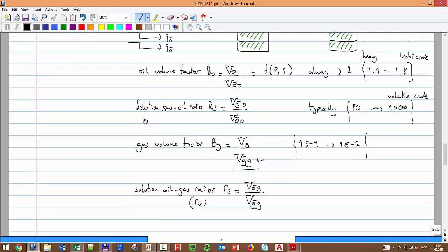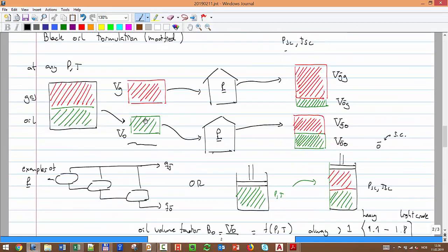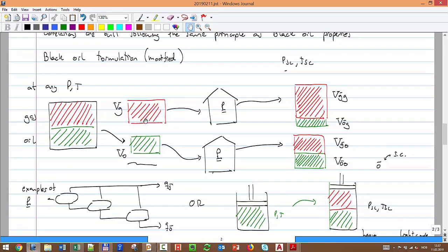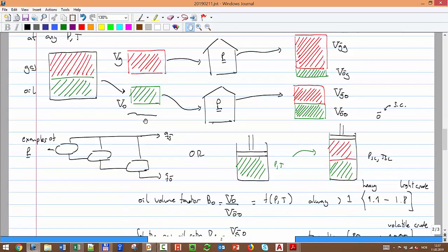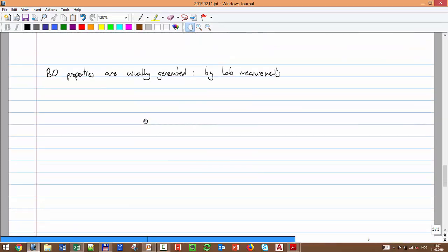I don't want to go into how they look with pressure and temperature. Just see that you have a ratio, and that's very practical, because if you have a volume that you measure in the separator here, you can know exactly how to convert it to local volumes of oil and gas. You have the ratio without doing any equation of state calculation, any equilibrium calculation, nothing. You just use the ratio that is computed on a table. Lab measurements, you can use a correlation.